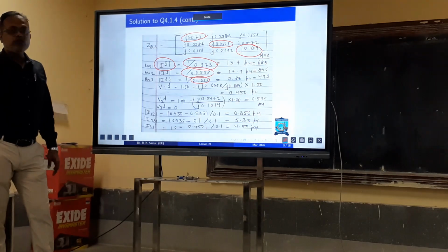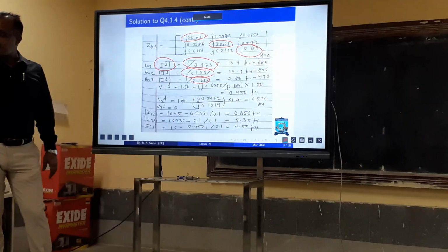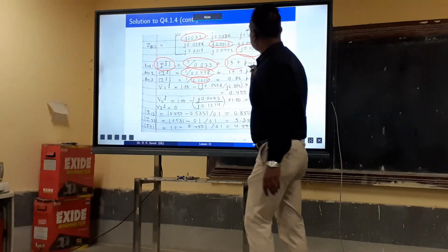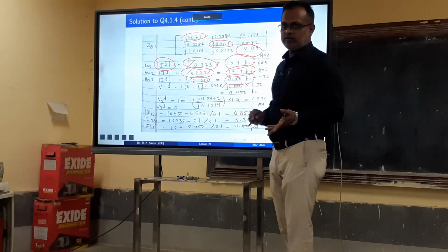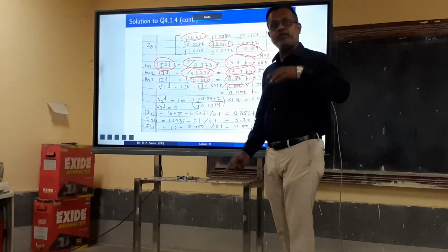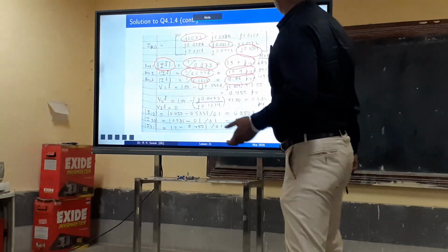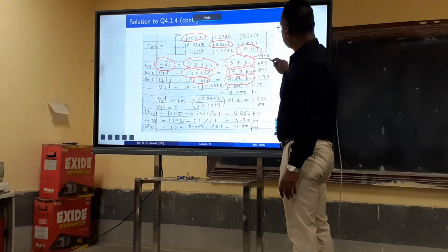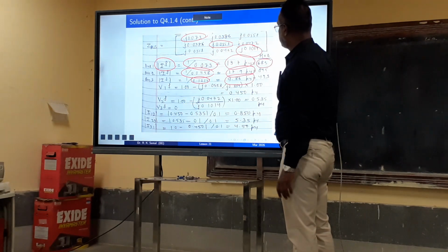So we are going to use the diagonal elements of the Zbus matrix to find out the fault level at different buses. This is the current value. Since the voltage is given to be 1 per unit, we can consider this to also be a short circuit capacity value. Suppose we have taken this, this is 685 MVA.